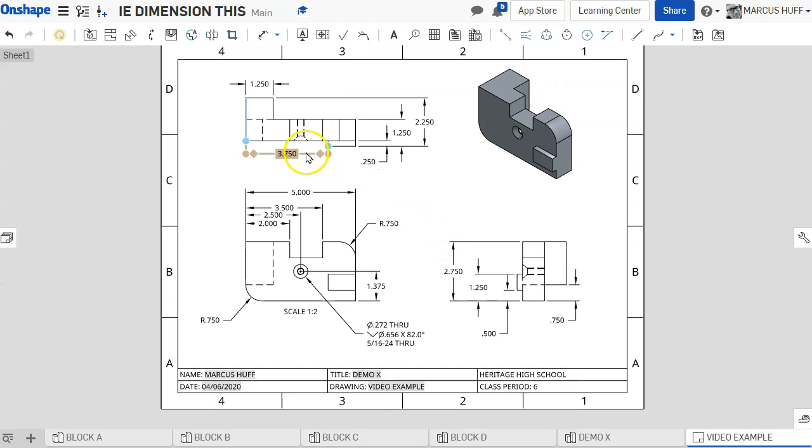Okay, so let's review what we did. We placed the top, front, and right projections, projecting from the front view from here to here, and here to here, and here to here. We made sure that we have everything related to width and height and depth described. We made sure to identify measurements for everything and placement for everything, including this hole. Notice that it's related to stuff we've already measured. And it's a good idea to choose one reference edge for all your measurements for one size. Like the width is all taken from this left edge to the right, left edge to the right. The height is taken from the bottom to the top, and the depth is from the front to the back.